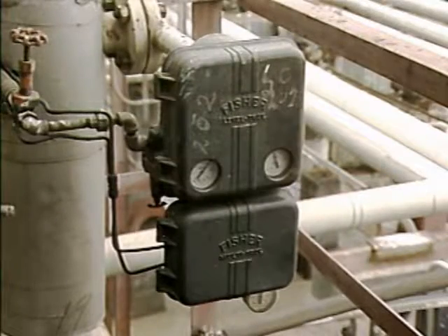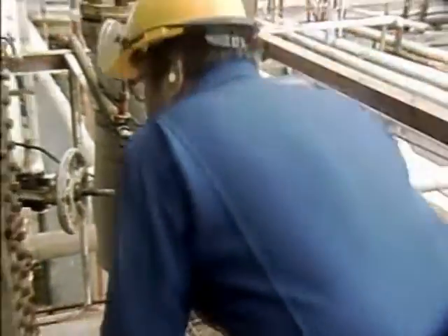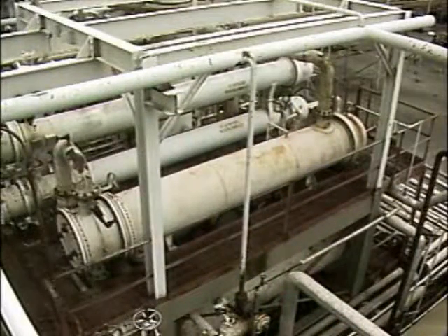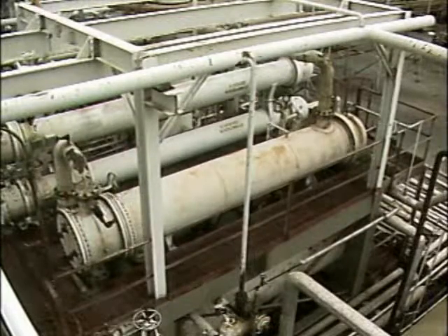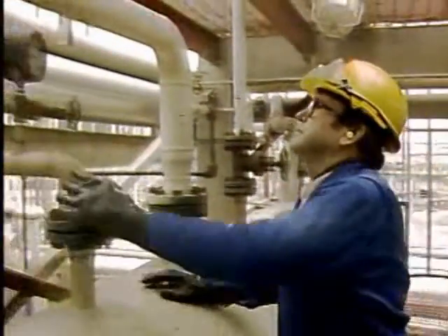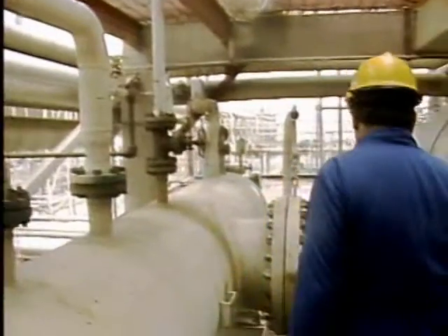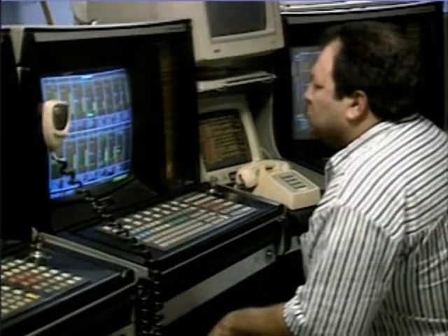A controller on the receiver automatically maintains level. An abnormal level could be an indication of a problem with the controller. A low level could also be an indication of a problem with the cooling water flowing through the condenser. Another important operator check is the unit's temperatures and pressures. These indications can be checked on instruments attached to the condenser or on displays in the control room.